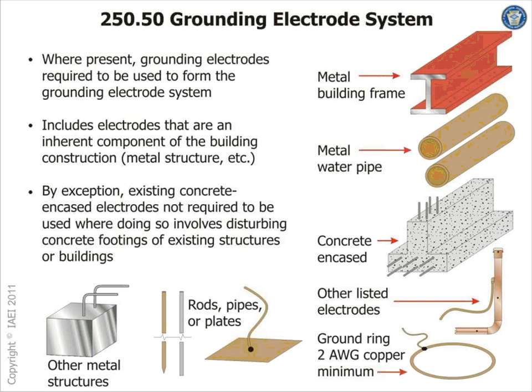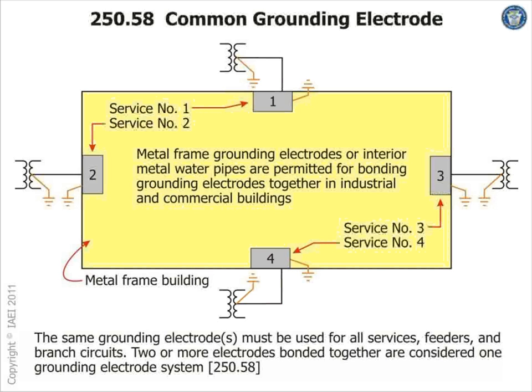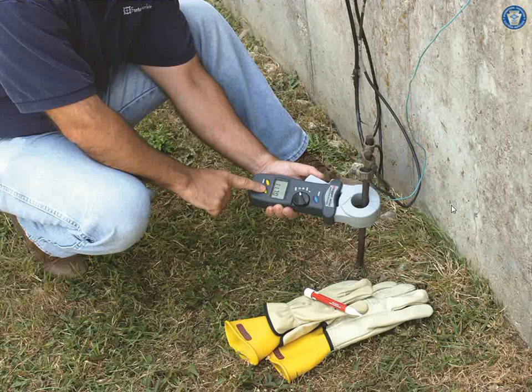These are a system, the grounding electrode system. I went through tying to the ground, all these ties. Here's what you said. If you have multiple systems coming to the building, you have to establish a grounding electrode system around the whole building and tie them all together. You can't just isolate them if they're coming to the same building.